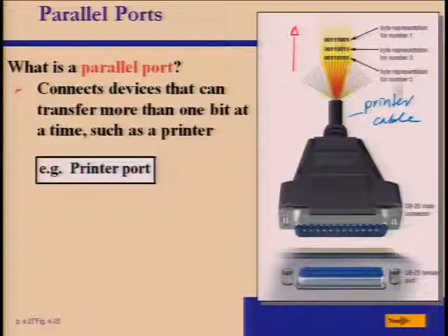So just now the same thing, the 3 numbers, 1, 3, and 5. We know that 1 is of this pattern, 3 is of the other pattern. So the data will be going out 8 bits in one go. That means for every single clock, 1 byte of data, 8 bits, will go out in one go to the external device. So if you compare this with the serial communication, it is at least 8 times faster, right? So you can have 8 bits in one go, right?